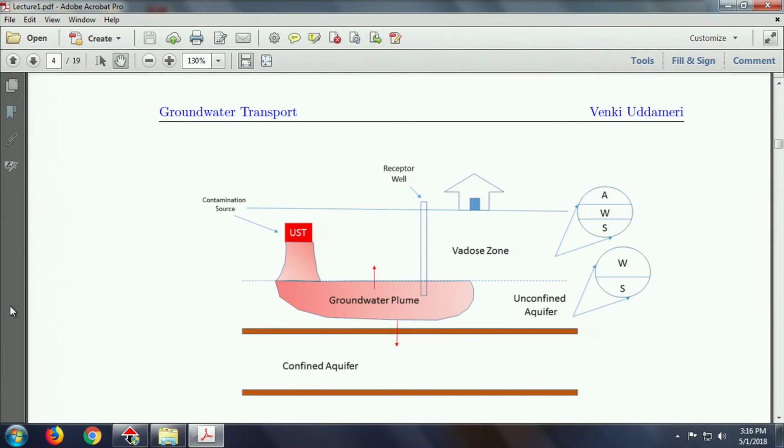Next thing we do is we somehow need to make the concentrations of that plume decline or decrease. How do we do it? Ex situ method would be to pump and treat. We don't want to do that. In situ method, somebody said chemical oxidation. How would you go about doing it in situ? You can do aeration. The key challenge to doing anything in situ